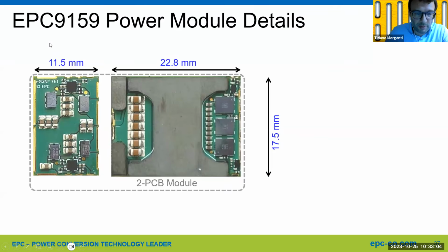This is the power module, full bridge board. And this is the board with the magnetics. We had to integrate the secondary side synchronous rectifier within the magnetic windings to reduce and minimize the leakage inductance and the voltage spikes on the synchronous rectifiers. So this is the input port, and this is a transformer which is capable of transferring 750 watts.